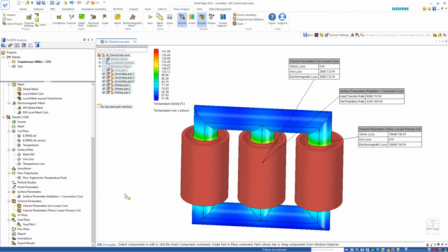So with this type of simulation, you can couple electromagnetic simulation with fluid flow simulation, all within one tool, within one solver run, running on an iterative basis. You don't have to do it iteration by iteration, because the electromagnetic changes are considered much faster than even transient CFD simulations. And therefore, these types of iterative approaches only work on several iteration bases, like 25 as we have set it in this model.